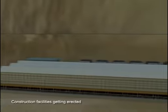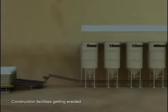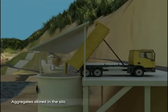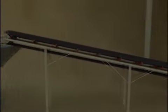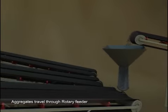Let us now understand in detail the trajectory of material movement involved in the process of building the dam structure. Dumper trucks travel via an approach road to the aggregate silos and dump the crushed aggregates in the respective silos. A conveyor carries aggregates from the silos, one size of aggregates at a time, to the rotary feeder.